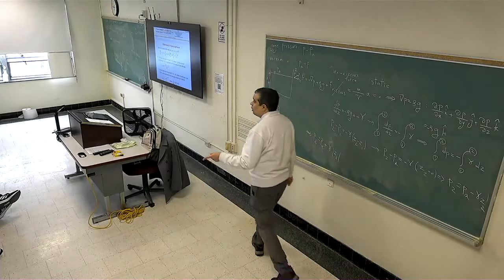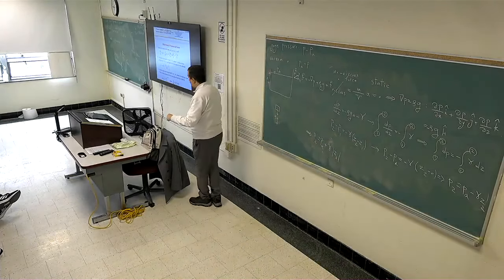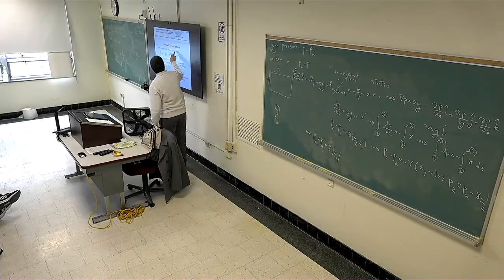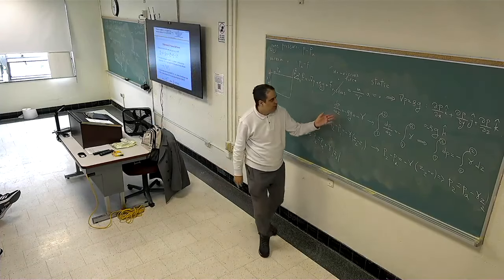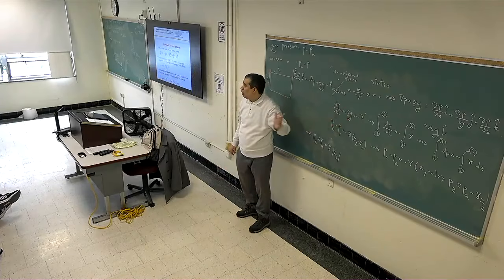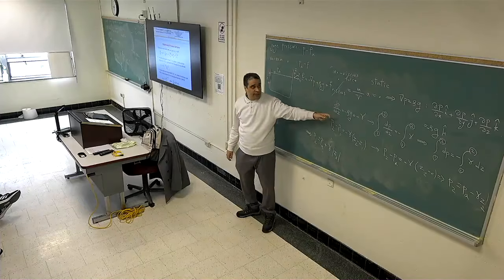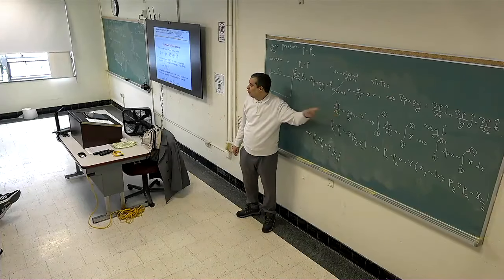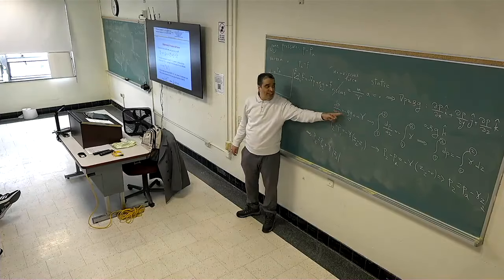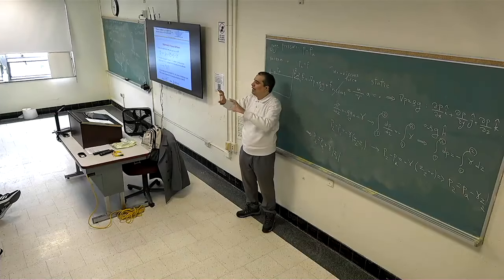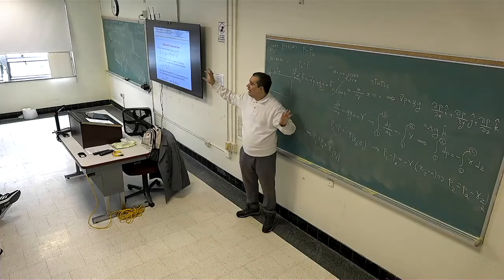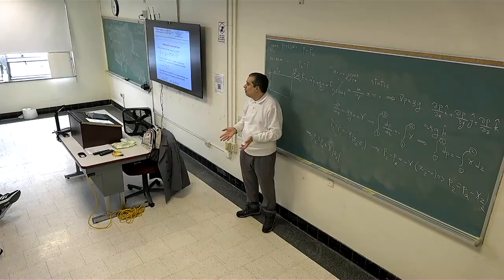But for gases, rho varies with pressure. For gases, we have P equal rho RT, the equation of state. So dP/dZ is equal to minus rho g, this equation. The equation is the same. But take a look at the board. Here, for liquids, rho is independent of P. So I can integrate the left side and right side without any trouble.